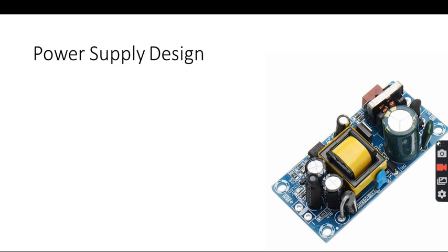If the size is getting down, then the voltage will get reduced. So when it was in the microcontrollers, we were using 5 volt and 3.3. When nanometer technology came, 3.3 and 1.8 started. If you go beyond that, they are telling that even 1 volt or 0.8 volt processing will happen. But anyway, we have to have a power supply for that. Any ICs or anything like that, you have to have a power supply. So we have to make sure that there is a power supply which is compatible for that IC.